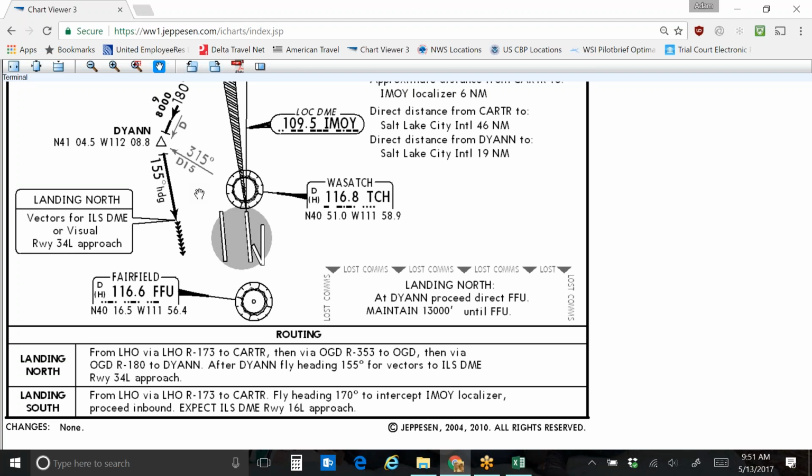And when it first went off, I don't even know what type of plane it was, but it shows you whether it's climbing or descending. It'll show its altitude, and then it'll have a down arrow at the end or an up arrow, meaning that it's descending or it's climbing. So it was climbing, and it said 9,000 feet, but with an up arrow, meaning that it was climbing up the canyon essentially. And you can see the dot moving north on our screen, and you can see us moving south. So it wasn't directly in our path, but it was coming at an angle right towards us. And it's climbing, we're descending. So you can start to see the recipe for an issue, basically.